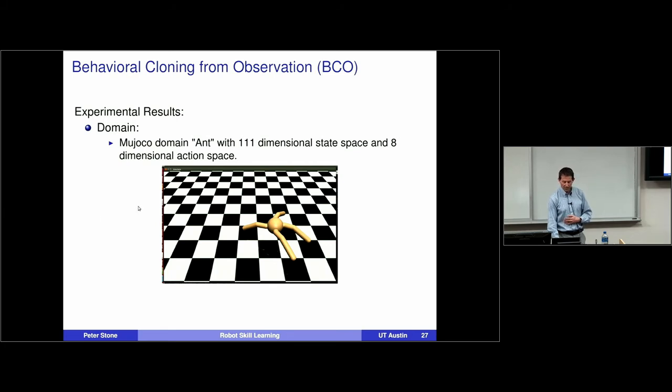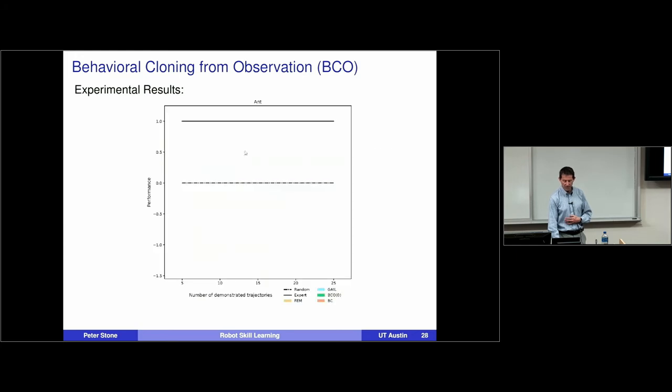In any case, the testbed environment for us is one of these MuJoCo domains. As I just showed in the video of this general methodology that I presented, we can compare the performance of the demonstration policy, normalized to 1 on this graph, and the random policy, normalized to 0. The fitness function here isn't actually just speed, it's also how close you are to the demonstrations in joint space.